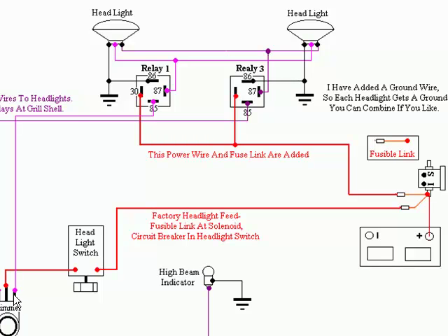And let's just look at the low beam, where then the current from the other direction flows this way here and going in there, and then this one here is connected to that one over there, and current is flowing in there and going back to the ground. And over here for the other one, current is flowing in here into the headlamp and to the ground.